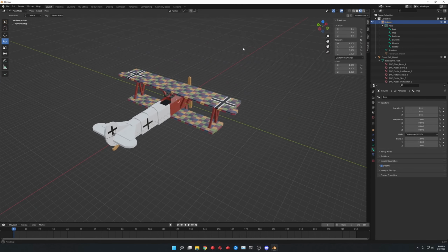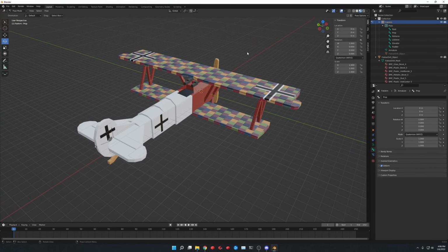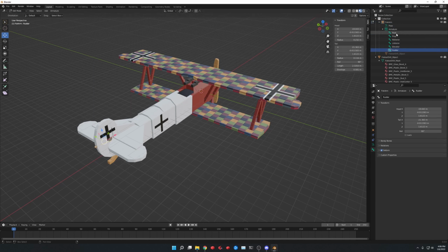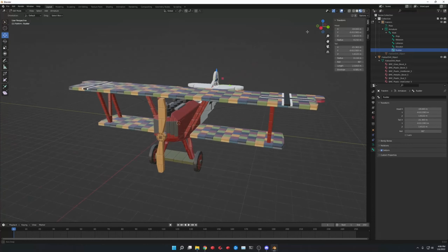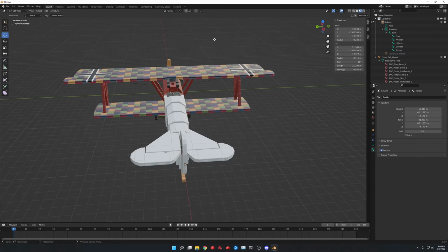Now we can put these bones in a way that Unreal Engine is going to like. So we're going to select all these bones and go into edit mode first. Select the root, then shift-select the rest, parent, make keep offset. We want the root to be the root. Okay, now the root is the root in the hierarchy. It's the parent of these children bones, and these are the bones actually doing all the magic.